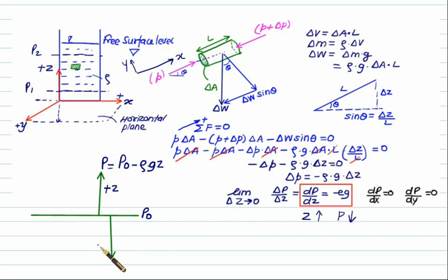But if you move below the reference level, in that case the pressure at this point will be equal to P0, and since here z is decreasing, the P will be increased. We'll write the positive sign. That will be equal to rho multiplied by g multiplied by z. So according to how much column you have changed, you can do your calculation.